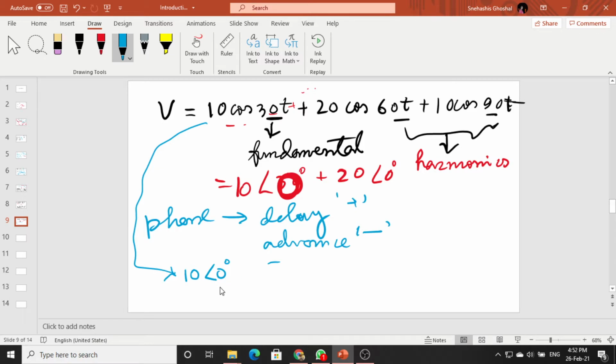That is the disadvantage. So in that case you have to treat each signal separately, using the concept of superposition. First you do your analysis by considering this part only, then you continue with this part, then with the third part. That's how the superposition theorem in AC works when multiple frequencies are there. Voltage and current of different frequencies cannot interact with each other. That you have to remember.